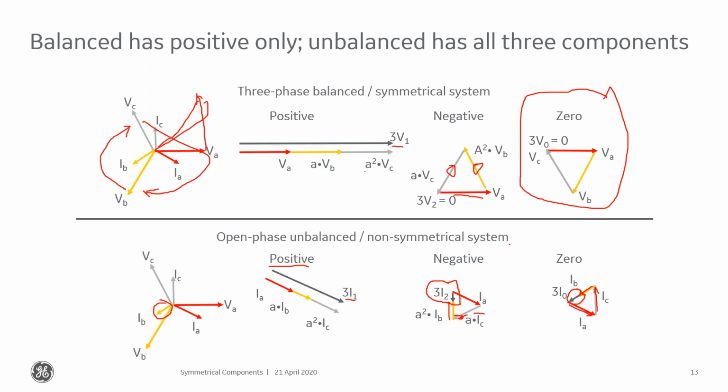Now, I mentioned that what this sort of looks like is maybe I've got an unequal impedance on the 3 phases. What this might also look like is if this is a medium voltage utility distribution system, and they've got a lot of radial taps, and they don't have their system balanced particularly well, then they might have this sort of scenario where they've got some zero sequence current that is just from this unbalanced load.